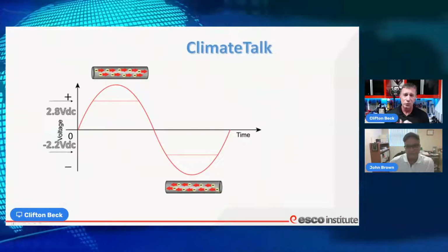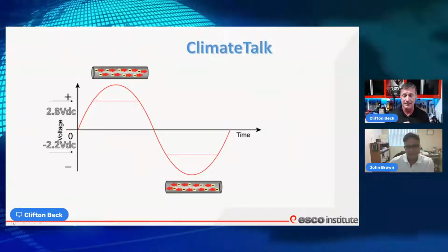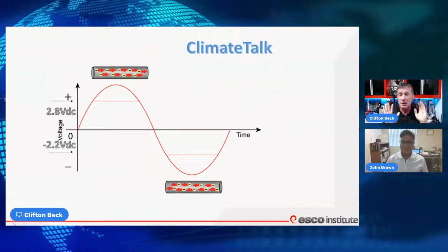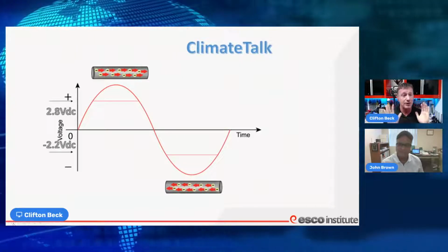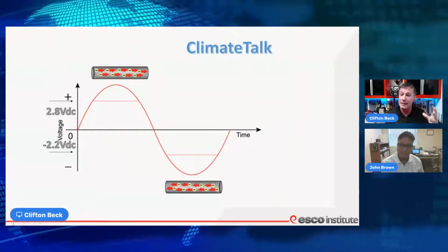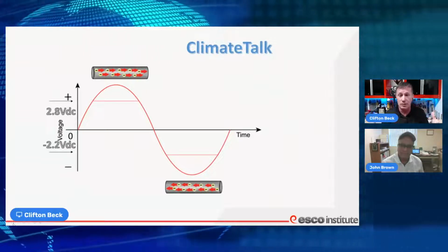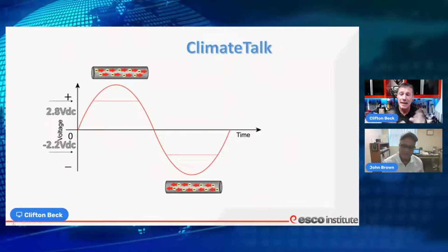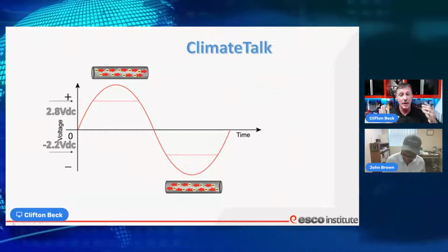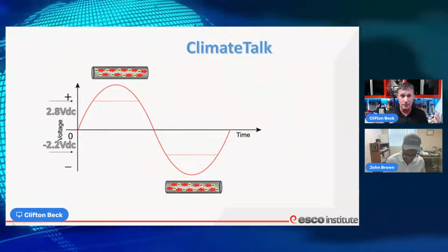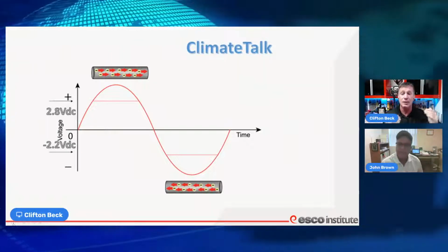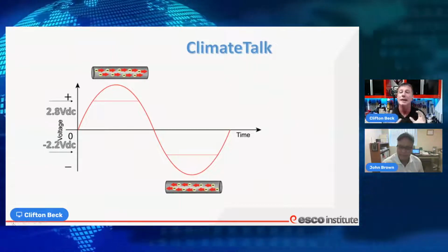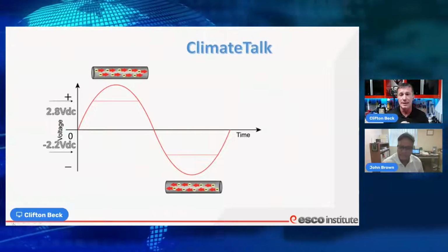Well, it's really not that complicated. It's very ingenious, but not incredibly complicated. We take our AC power source, starting at the furnace or air handler, our indoor unit, which is where our power source originates typically, right? That's where the power supply is. So we take our AC signal, we run that through some bridge rectification. We run it through diodes. We get that rectified into a DC signal, a reduced DC signal at about 5 volts DC.